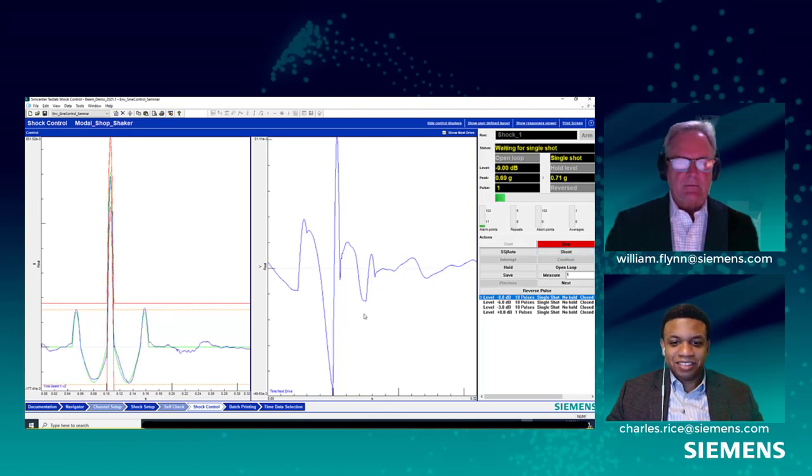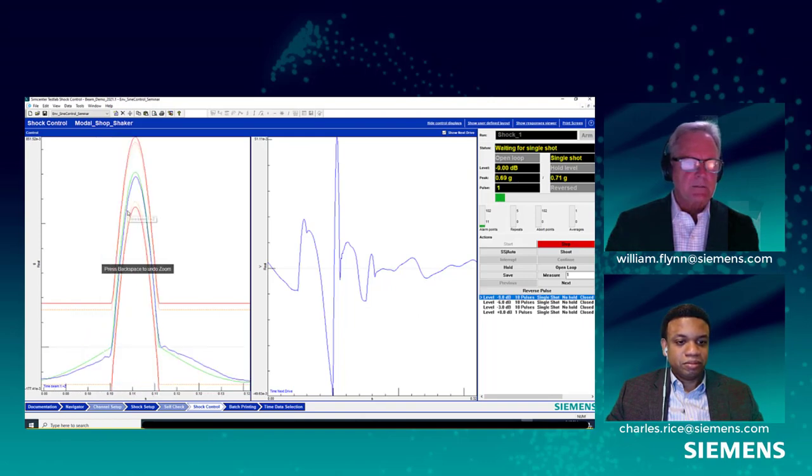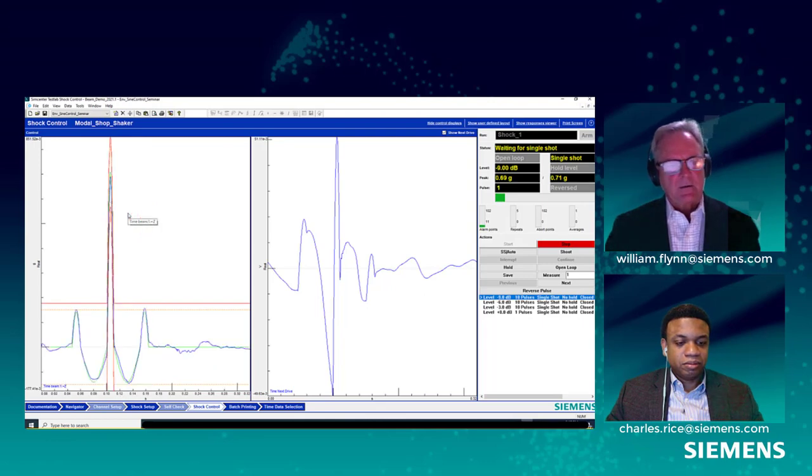You can see the drive out here is the predicted drive. There are phase relationships between acceleration and displacement, and also, of course, based on the transfer function of G's per volt with this system, that allows me to calculate the voltage out of my DAC, shown in this display here. It's showing some pretty good response just from the initial estimation from the self-check of my transfer function.